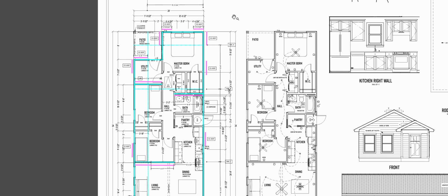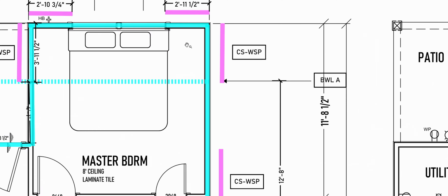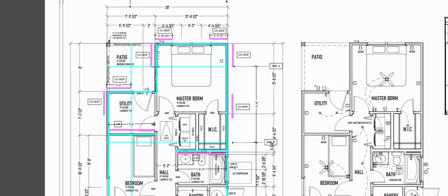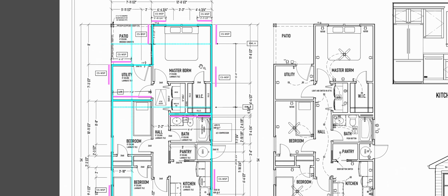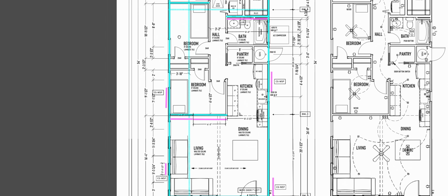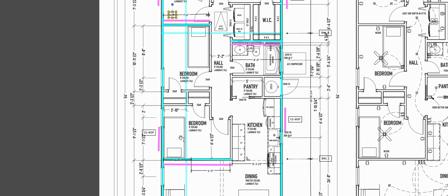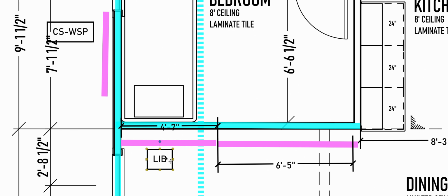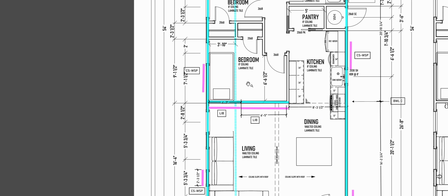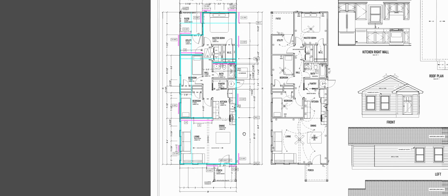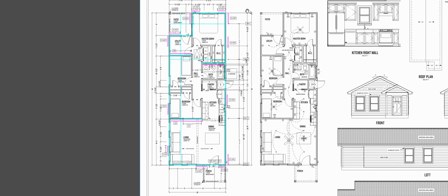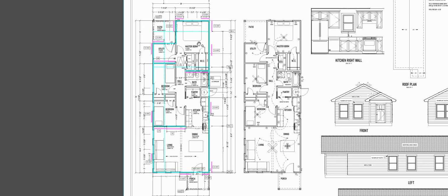So the more thorough you are in labeling all the stuff that's on here, the better the other people can follow your plan. But I'm not teaching you how to make a clean looking plan. I'm teaching you how to know that your house isn't going to fall down. So that takes care of all the outside. We got lead and brace marked there. Let's go ahead and copy that. Put it here, and because there's a second one, I'll put it like here, I guess. 2 lead and braces. All right. All the panels and types are marked. Now we need to know if we're going to pass the length test, and we're going to do that in the next video.